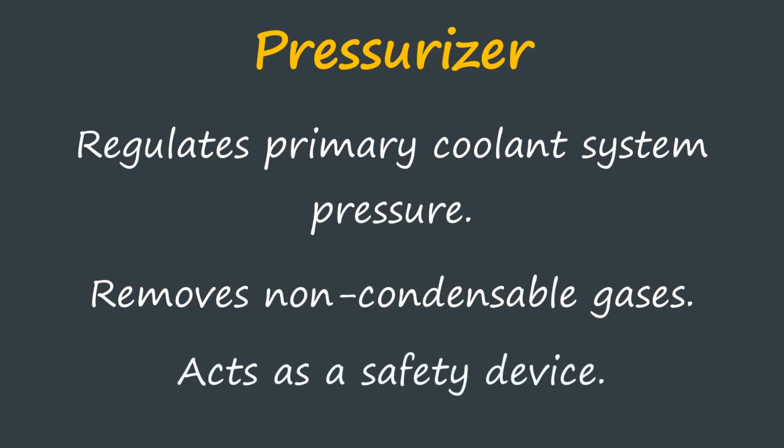We measure the water level within our pressurizer, and we mount the pressurizer itself at a higher level than our steam generators and all other parts of the PWR. We do this because if the water level should decrease, we're going to get an alarm before the coolant level drops below a critical height and we damage some of our power plant parts. For example, we don't want the primary coolant dropping so low that the reactor core is no longer surrounded by coolant. Primary coolant is a coolant, it cools the reactor core.